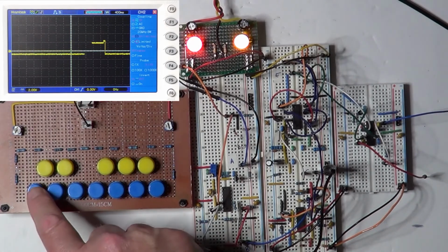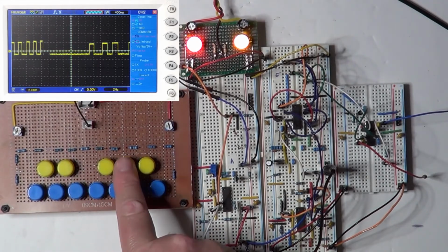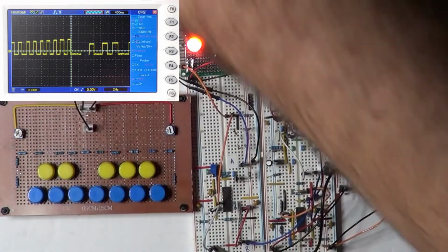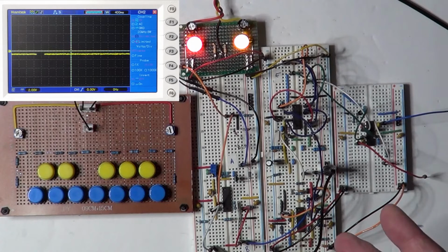And so yeah, this works fine too for all the keys. You can see that they progressively go higher and higher, following the rule that from the first key to the last there is a total of 1 volt of difference. And that's it, everything works fine, so I guess we are done with prototyping and we can now actually build this circuit. So let's conclude our discussion.